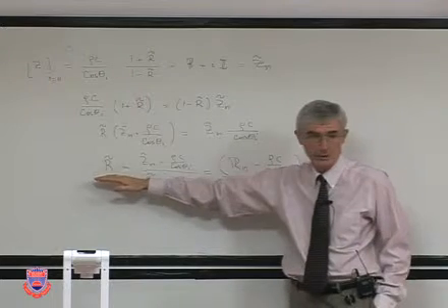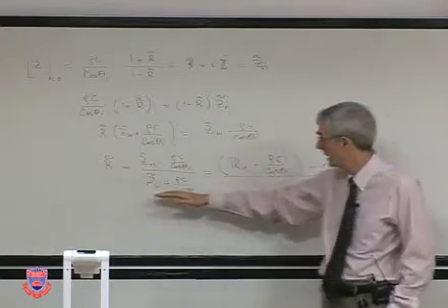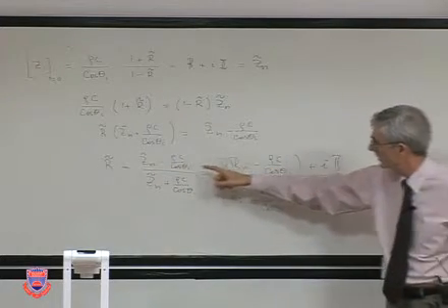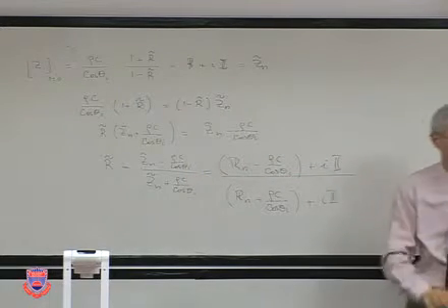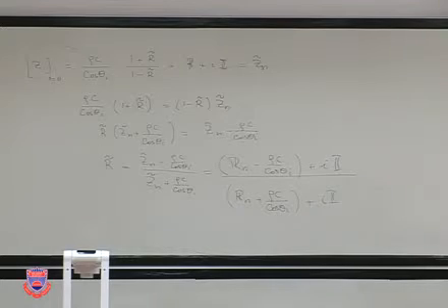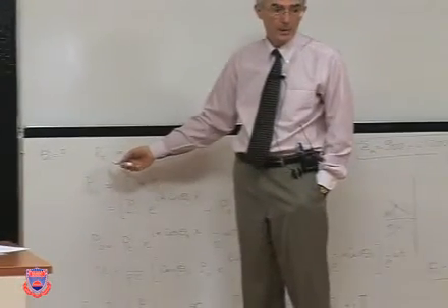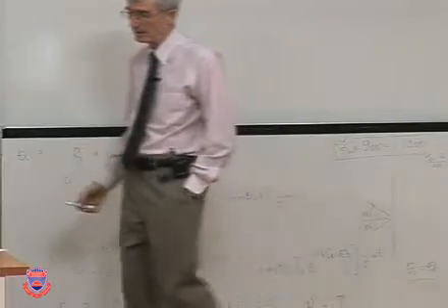And you have an expression, R being the coefficient of reflection. So you have a complex expression, and we separate the real and imaginary parts. This is the coefficient of reflection for the pressure waves. Now the question was, what makes the power reflection coefficient minimum? What is the angle that makes it minimum?